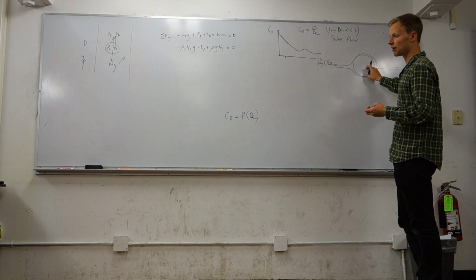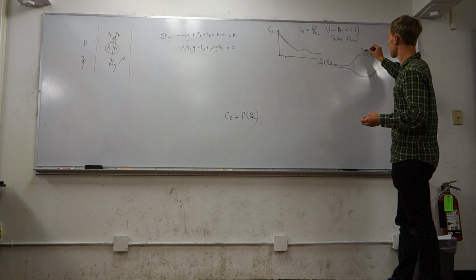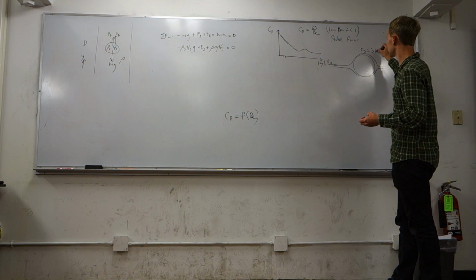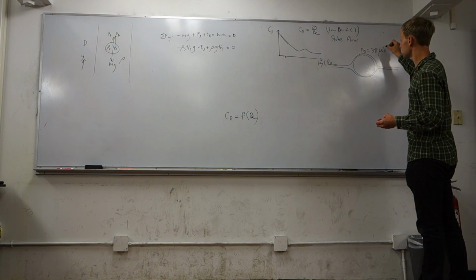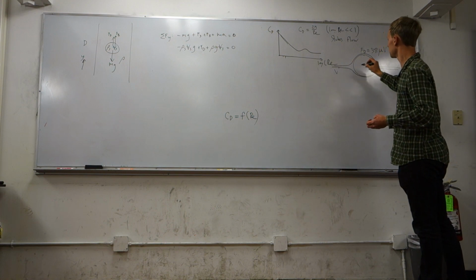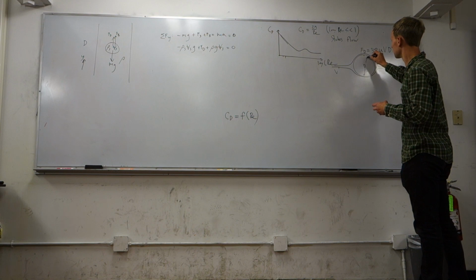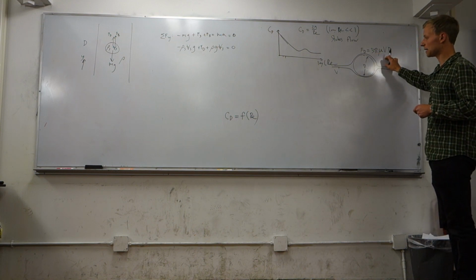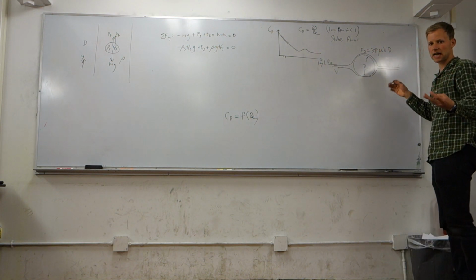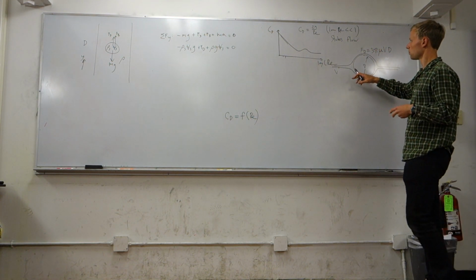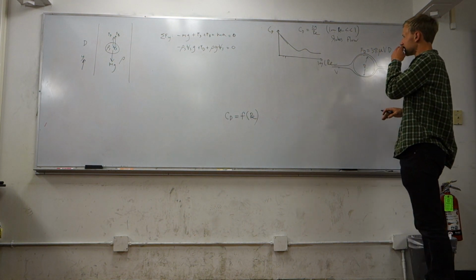And what we pull out from Navier-Stokes equations, and this you have to take my word for it, is that the drag force on this sphere is equal to 3 times pi times the viscosity of the fluid times the velocity, this is some v, times the diameter of the sphere. Now keep this in mind, we're going to get this using our experiment in a second. I'm just telling you that there's two ways of getting out what this relationship will be. One is experiment and one is with theory.